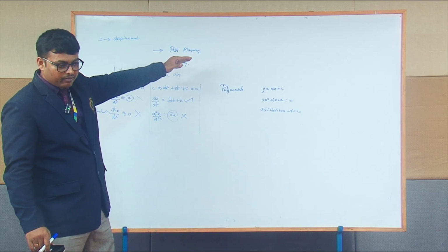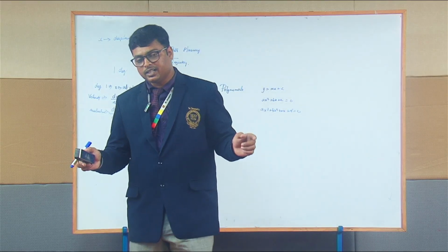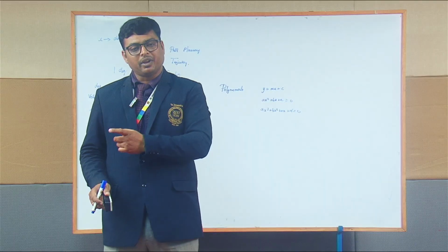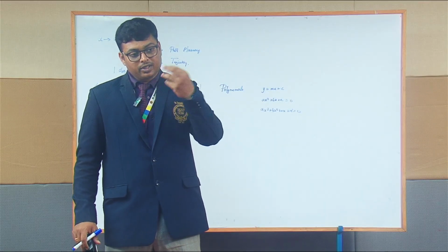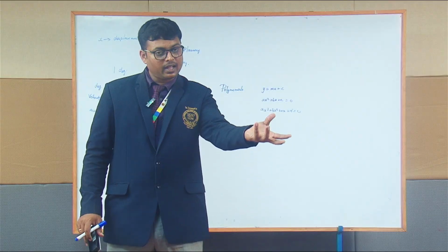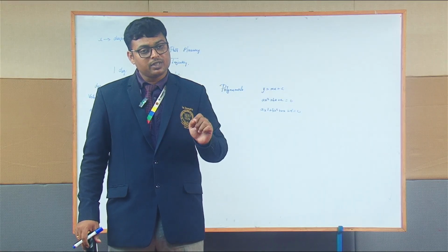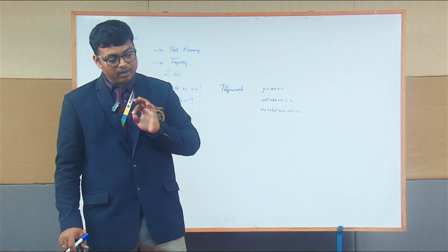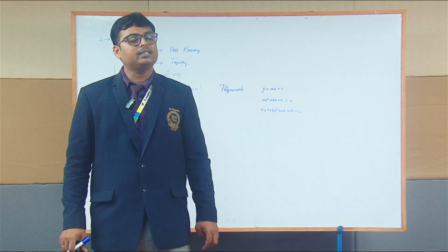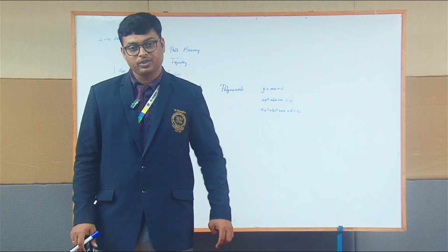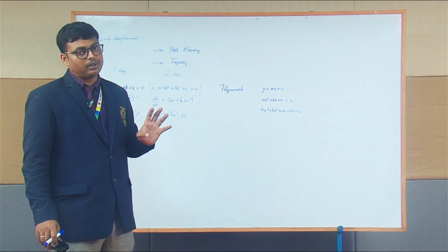Again, I am giving you a clarification: planning a path is nothing but a starting and destination point governed by intermediary locations, whereas a trajectory is all about the future prediction of the next location with respect to velocity and acceleration. It also governs the path, but we are very specific towards velocity and acceleration. So whenever you design a path for the robot, you require a velocity profile as well as an acceleration profile with respect to intermediary points. So this is all about understanding robots with respect to path planning.